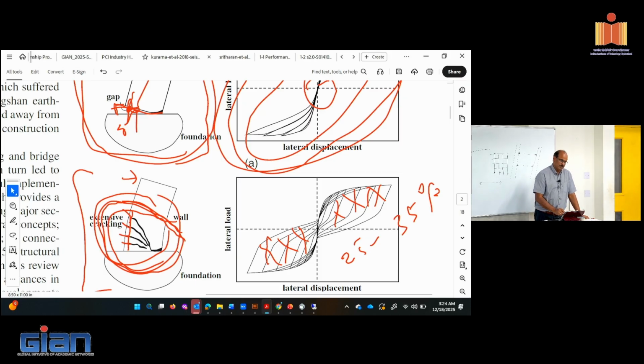It's not going to be as much as cast in place, but I would argue that probably we don't need that much energy dissipation. So we did do a series of studies to see what would be the minimum energy dissipation I would need. And we were able to show if you have 8-10% range is more than enough. Current code, the ACI, asks for 18%. Because they come from this world of 25-35, so we brought it down to 18.